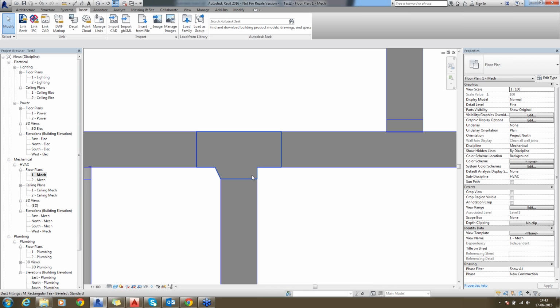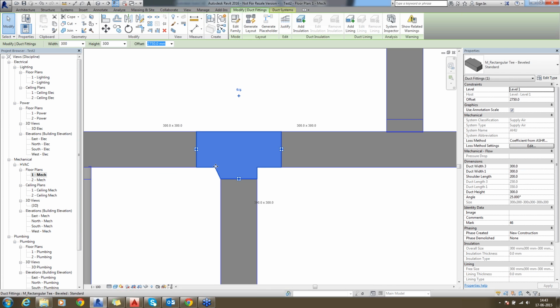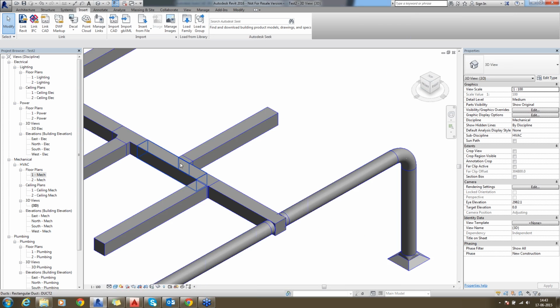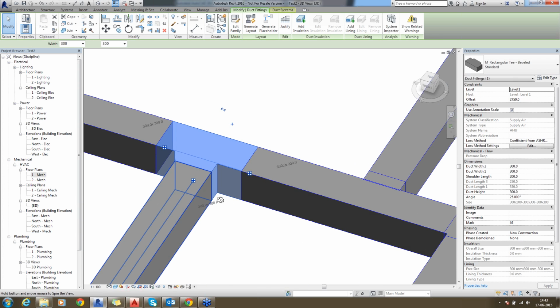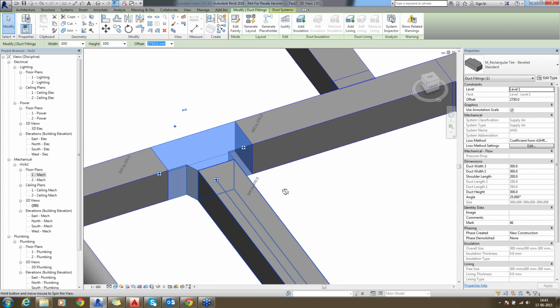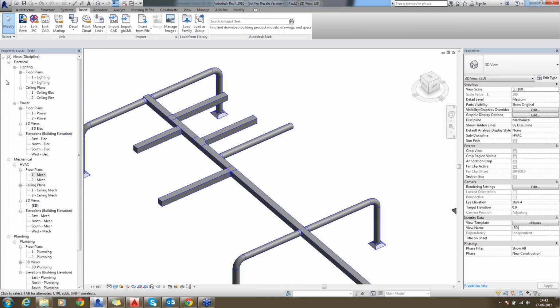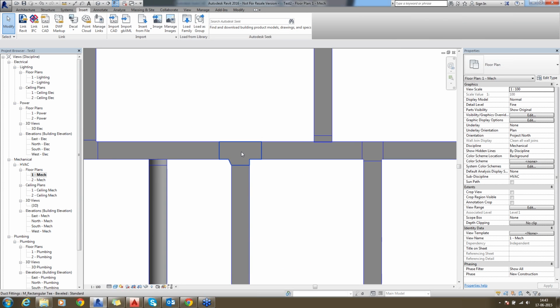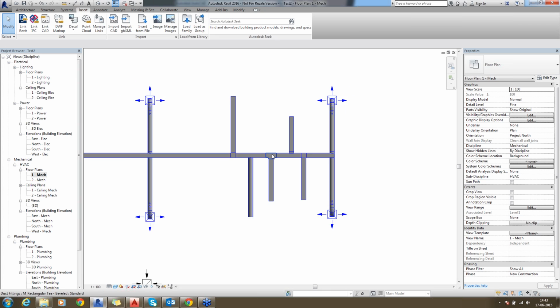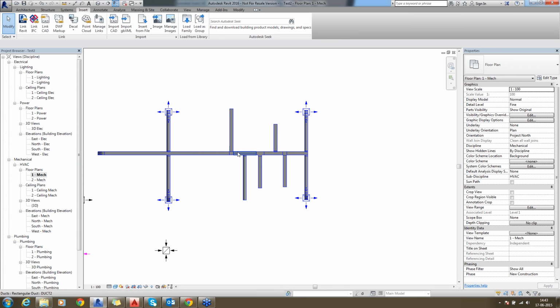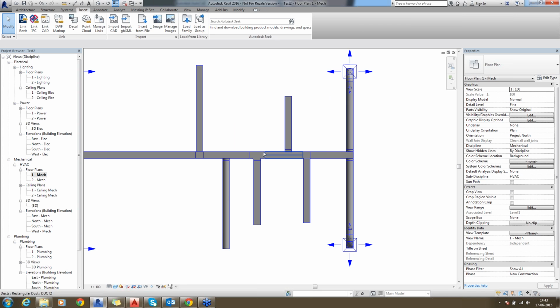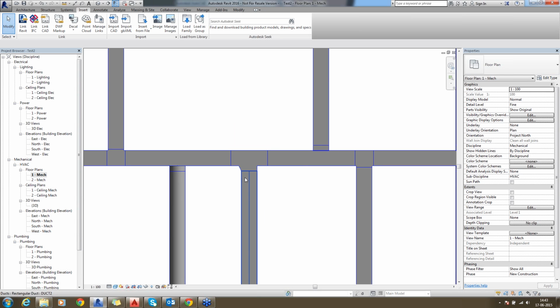See the difference here. This kind of structure we call beveled. See, while doing duct routing, we should concentrate on this. For example, our air is coming like this from the AHU. This flow should be like this to avoid friction loss.